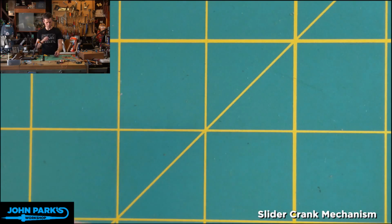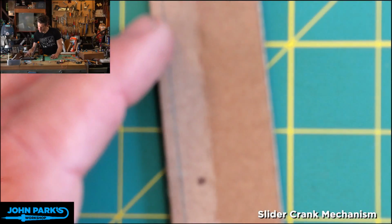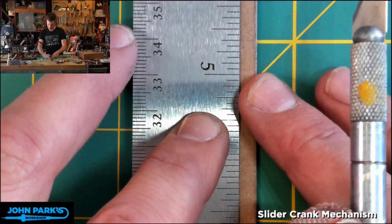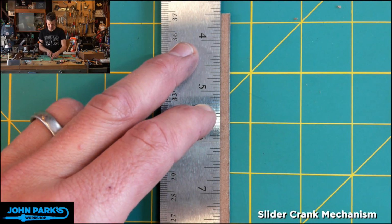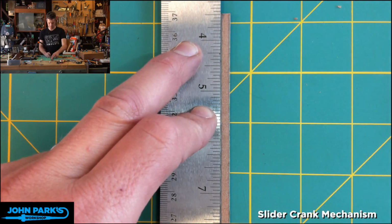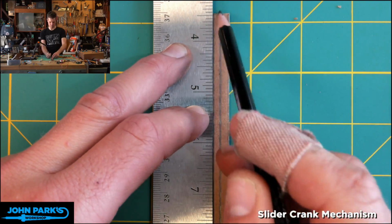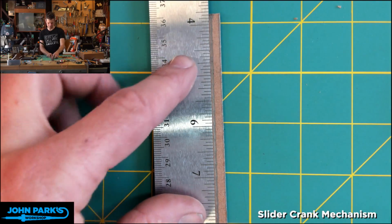Another way that you can deal with those is by cutting out, let me make sure we're focused here, cutting out a channel. So let's try to do it with this one as well. So I'm going to put a couple marks in this, sometimes it is easier to mark it and cut it and not just try to cut it. So that'll be one. That'll be another. And the issue is that you can't really compress the cardboard infinitely into itself. So by removing a little channel, you can get a nice bend. So this will be bending opposite direction of that first one.